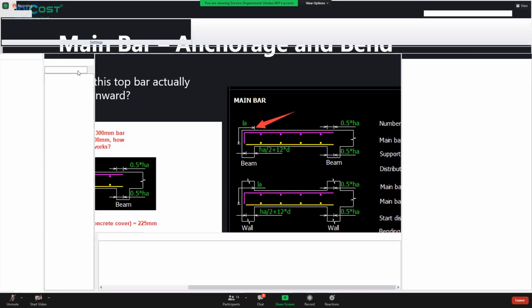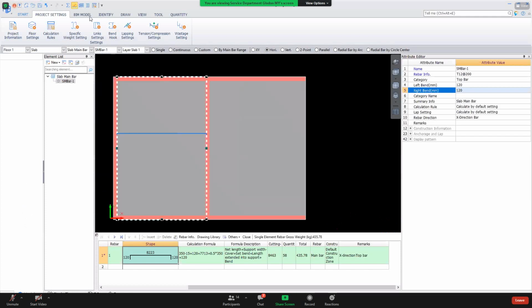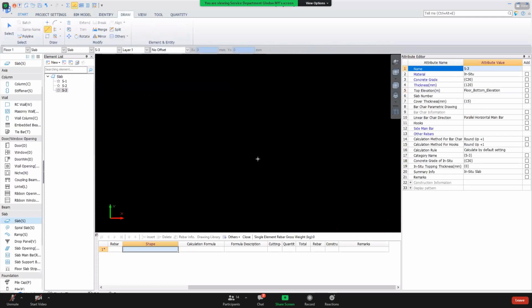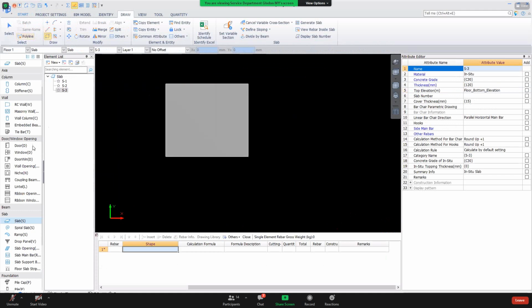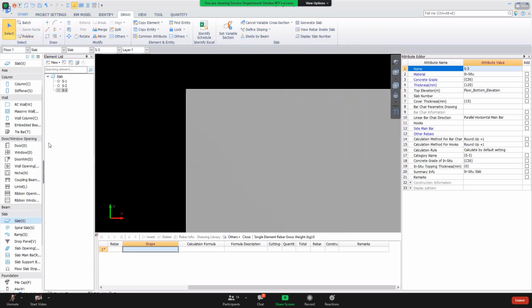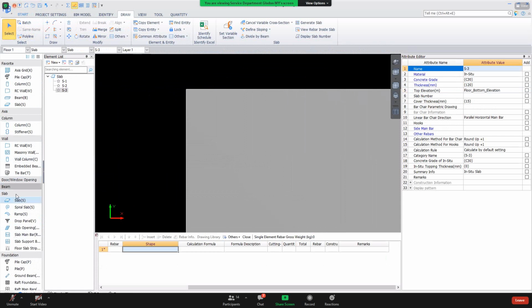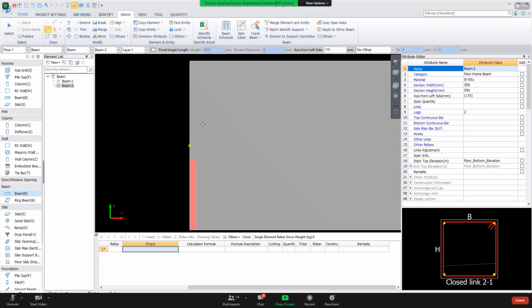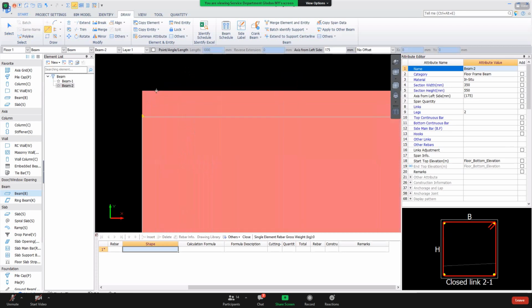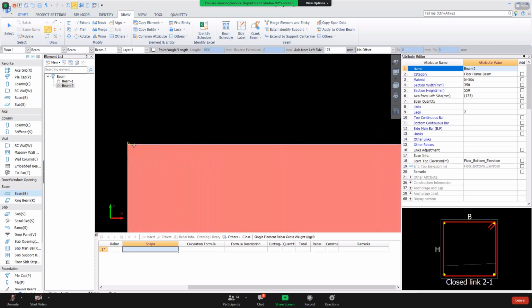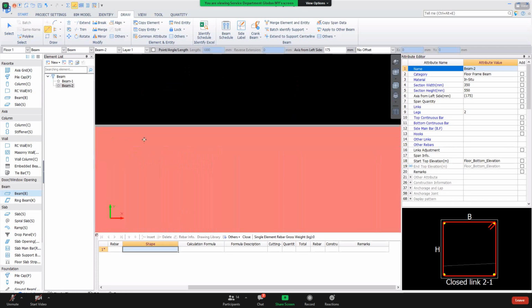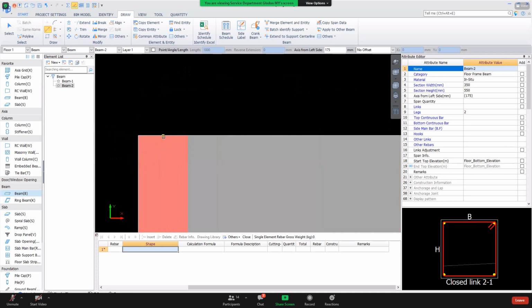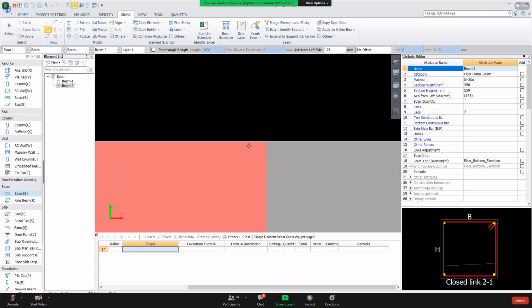Let's say the type of common error that people will usually face is when they draw a slab first, and then only draw the beam. So when they draw the beam, what happens is this. Here they draw correctly. And then there are certain times where you accidentally draw until the edge like this. You can see that there is a small gap over here, but when you zoom out, you can't see the gap. So there are situations that people draw like this. See, you got a gap over there.